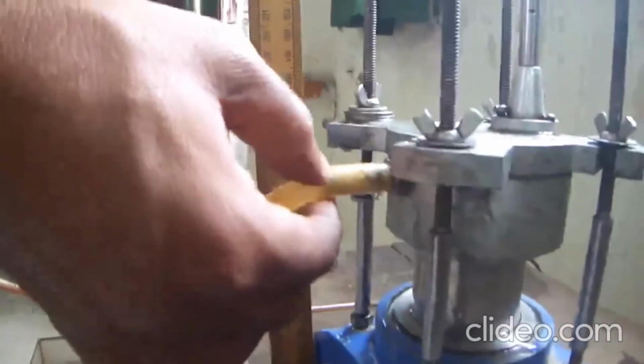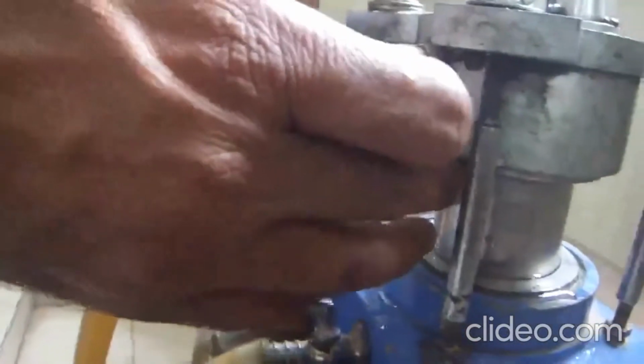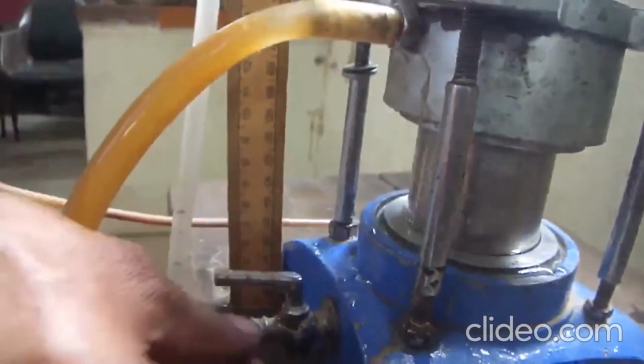It is maintained from here till here on the top of this soil surface or center of this pipe, which is subjected to supply the water. And once water is going with this head on this sample, it is passing through this sample and coming out from this tap, which we need to collect for a certain period of time, that is basically delta T.